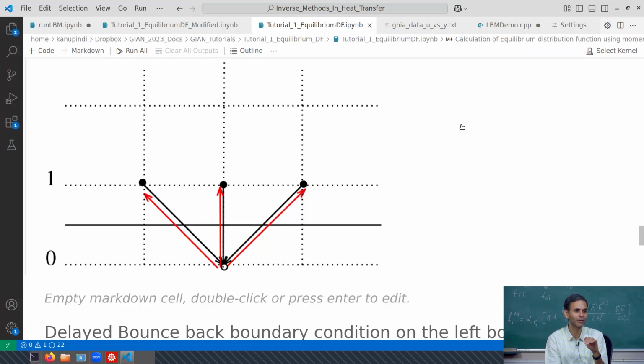The black line is actually the physical boundary, right? Because this is a dry node boundary condition, correct? So my links are stored at 0, 1, 2 and so on. For example, if you see here, I have drawn two sets of white lines, right? In between I have drawn the blue line, and the blue line is where my boundary is physically sitting. It actually doesn't correspond to any of the nodes, because that is how the dry node formulation came about, right? If you look at the wet node formulation, then it will lie with one of them, it will lie with the outermost one, correct?